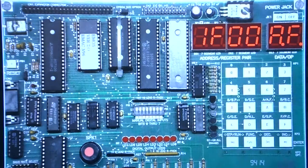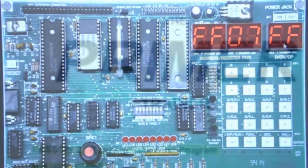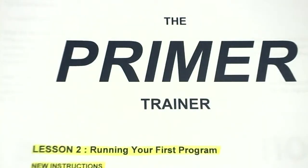If we want to change to another memory location, we can go to function, and we're looking for the program counter, and instead of FF01, let's check what's in FF07. So we can put in FF07 and press enter, and it shows us our program at FF07 is indeed the FF that we stored there. So this concludes lesson number 1.